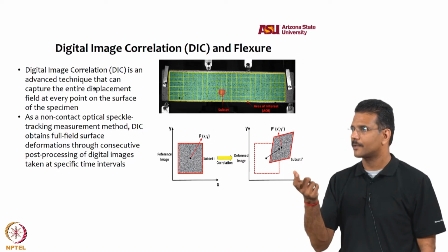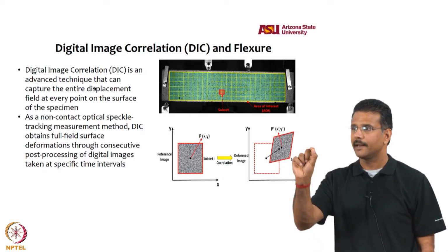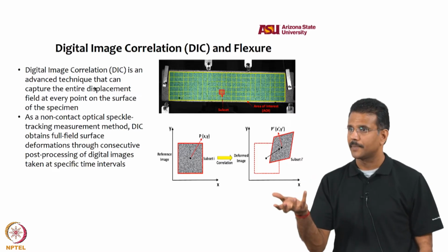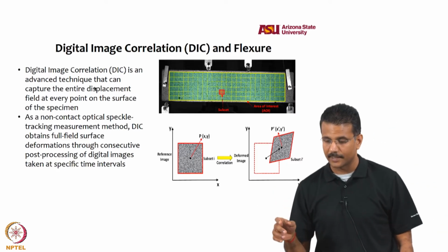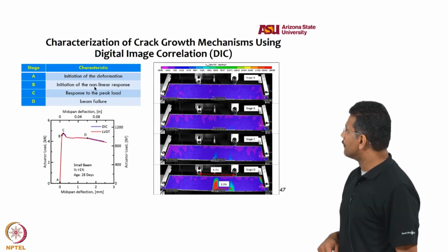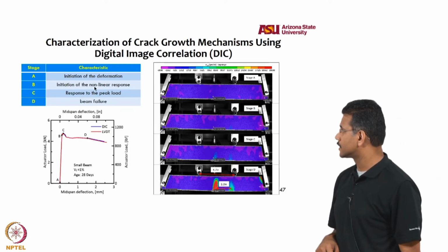Basically it is like surface strains, right. A point moves from here to there, and the change in distance divided by the initial distance is the strain of that point, and you convert that into a Lagrangian strain field. Okay. So, just to give you a few important points in the load deformation plot.